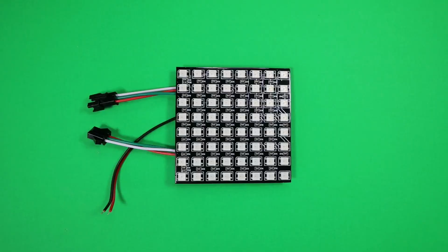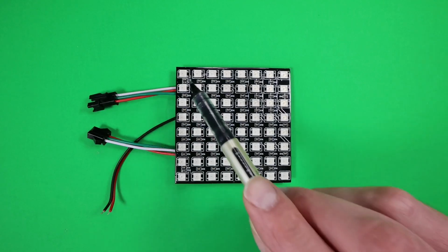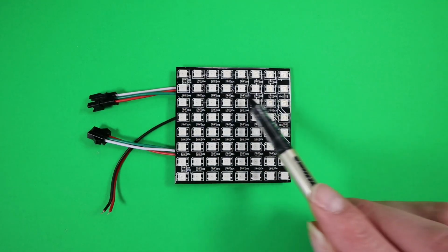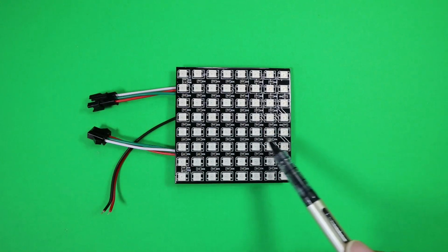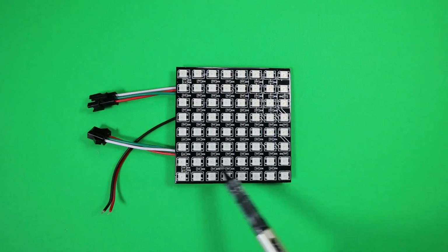One final modification that I've not implemented and is left as an exercise for the viewer is to add support for a matrix of LEDs instead of a strip, as this layout of LEDs doesn't look good when it's treated as a strip. To support this, a rectangle instead of a strip will need to be taken from the noise image and moved around. If you take this route, be aware that it is normal in these types of devices for the LEDs to be ordered in a zigzag fashion, going forwards then backwards as you move down the rows. So this will need to be taken into account when updating code.